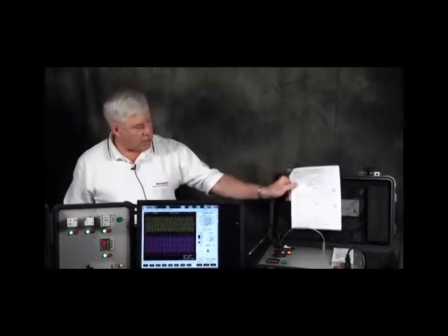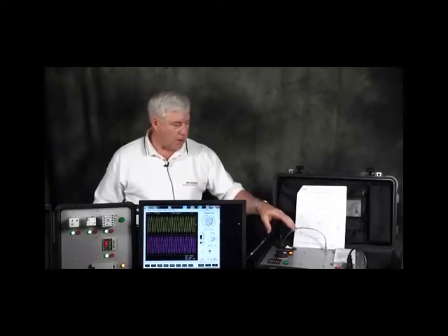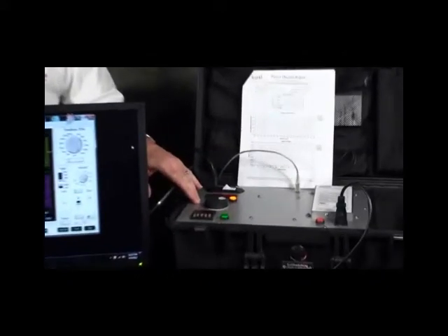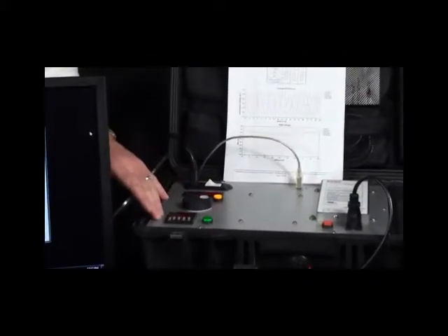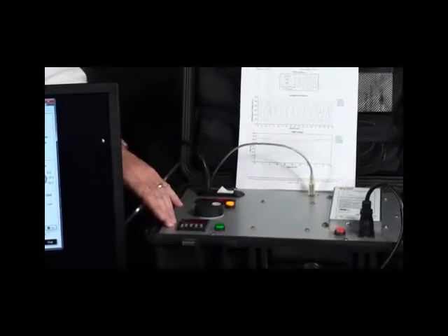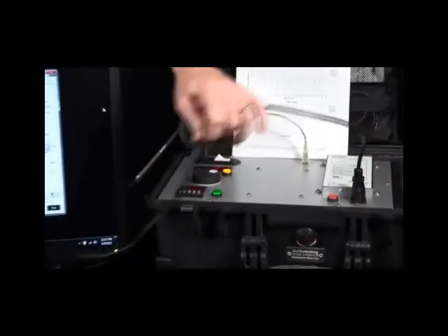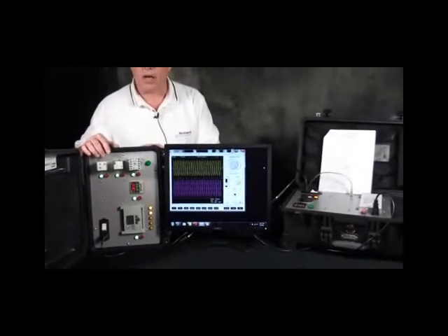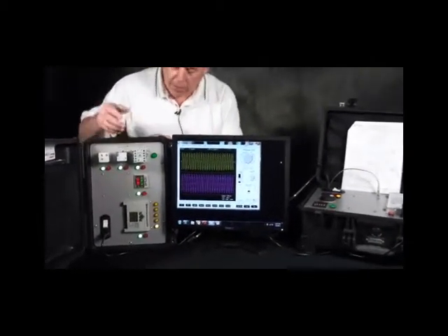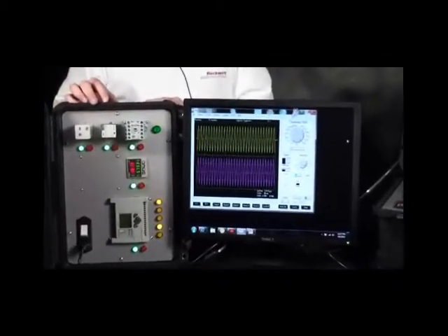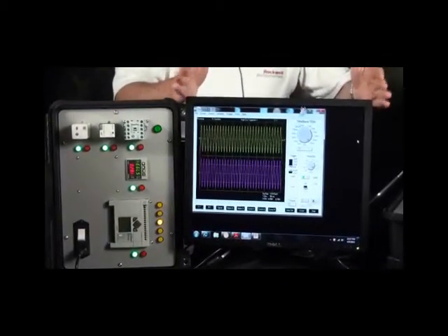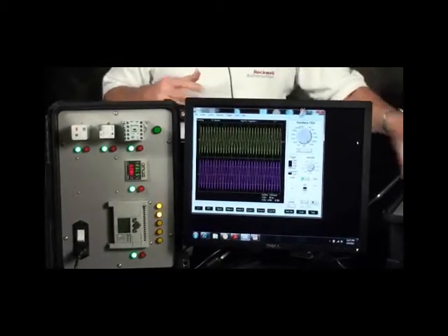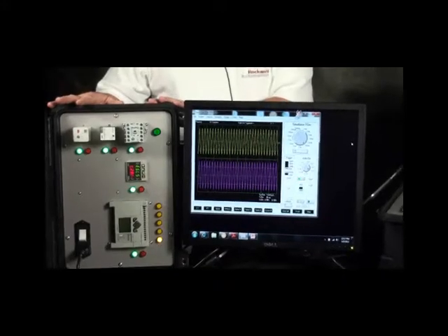To accomplish this demonstration, we're going to use some very special equipment. I have with me a sag generator. This actually allows me to dial in the voltage and how low it goes, and for what length of time we sag the equipment. We're going to sag the equipment over here on my right, which is our control panel equipment. Typical contacts, relays, power supplies, encoders, and of course a PLC. In between, I've got a scope that actually allows us to see what the sag generator is creating and what the load is actually seeing with the events.